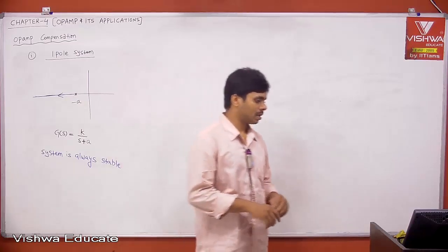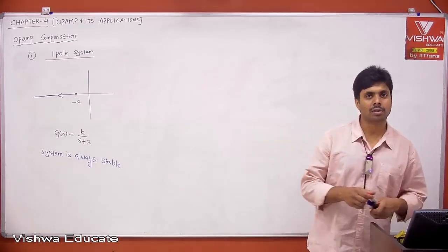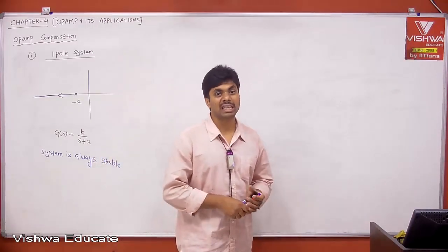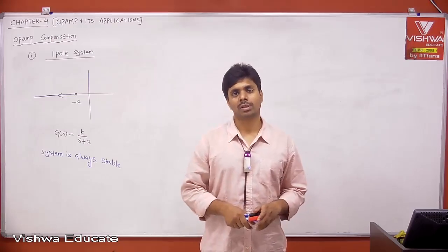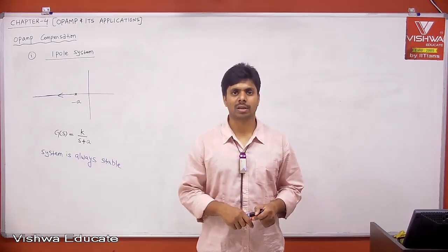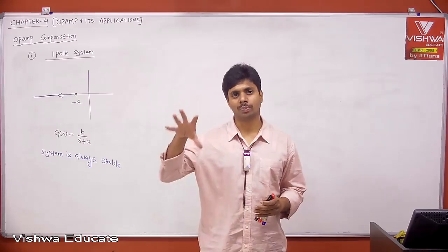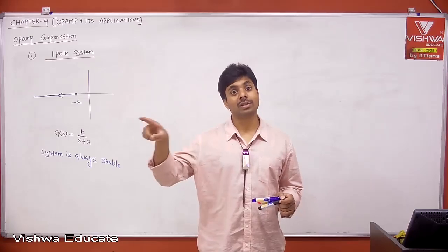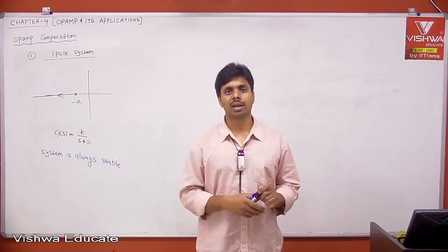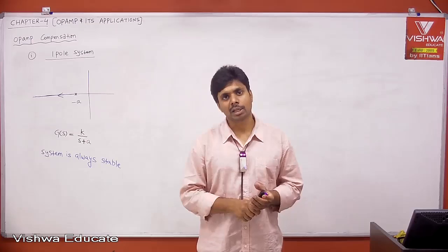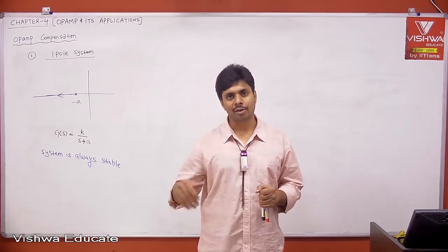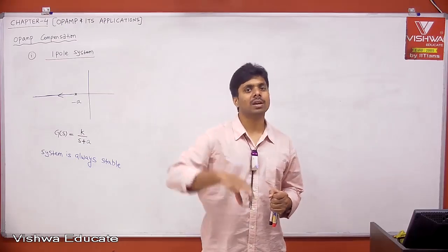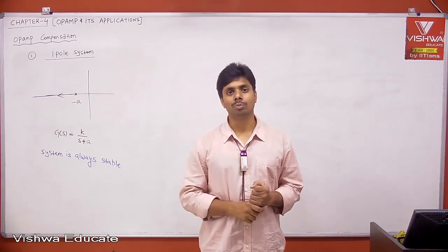Welcome back. In the last session, we were talking about system stability. I explained clearly a point: when people say one pole system, two pole system, three pole system, that is associated with the open loop system's number of poles. Therefore, when I say open loop system's number of poles with unity gain feedback, that is what we consider in control systems. Remember, practically you may have H of S, then we have to consider a unity gain feedback system, then just put that H of S into your G of S, and effectively that will become the loop gain.